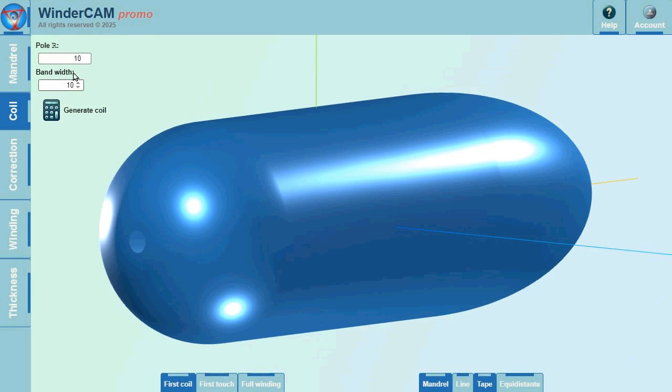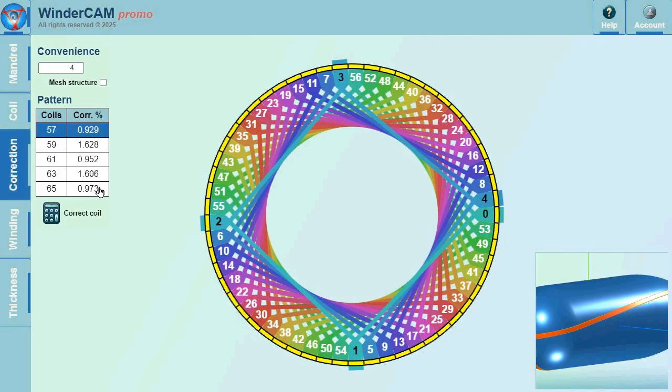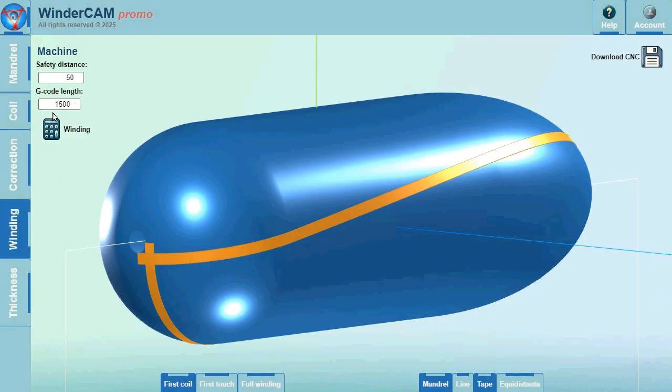After entering the parameters, the website calculates the shape of the tape coil, the trajectories of the mandrel, and the mechanism links, and then encodes the result into a control program format for the machine tool CNC. Based on the calculated layering scheme, the program automatically determines the change in layer thickness along the entire profile. The screen displays a graph of the thickness change, allowing you to evaluate the thickening of the shell at the pole holes. After winding the first layer, the intermediate outer contour becomes the inner contour for the next layer.